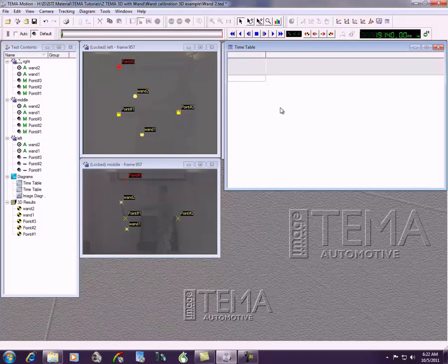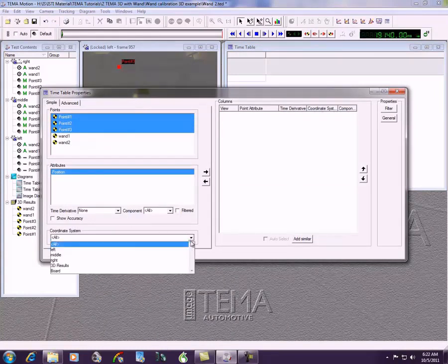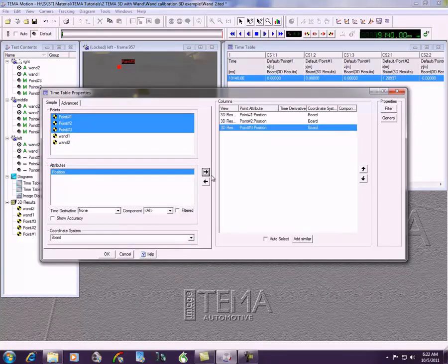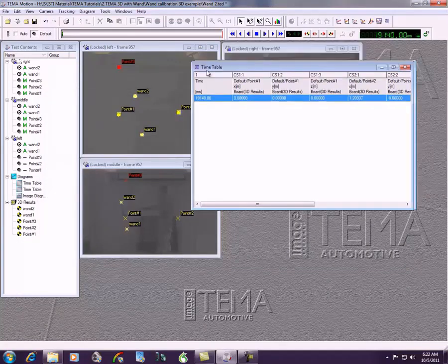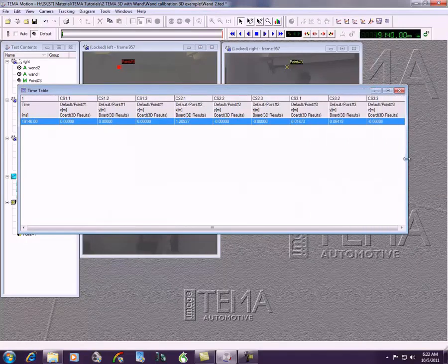Note that the coordinate system we established was in one frame only, but is valid for all frames as the cameras are not moving. If the cameras are moving, then the 3 points need to be tracked in all frames and a dynamic coordinate system requested instead of a static one. Now we're ready to track moving targets and plot their 3D motion.